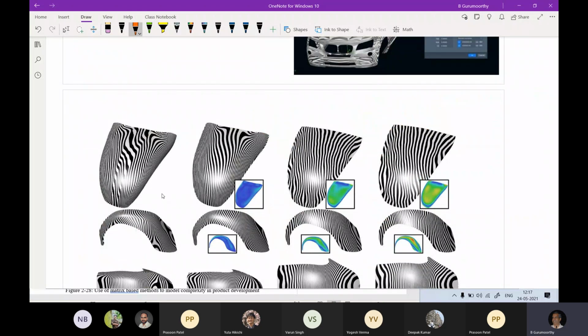As you can see between the first two images here, grossly the zebra plots look the same, but you can see that there are a lot of wriggles in the zebra plot locally here. There are additional bends. There is an overall bend in the surface, which is okay, as you see here as well. But other than that, the lines are looking very sharp and crisp. And so this will be deemed a better quality surface than the one that you see on the left here.